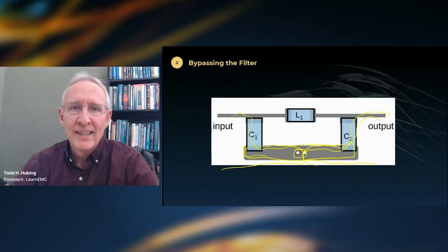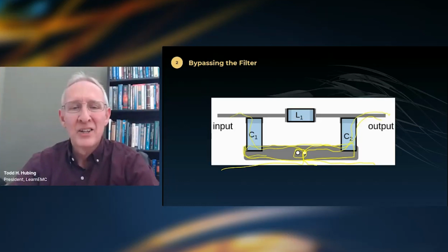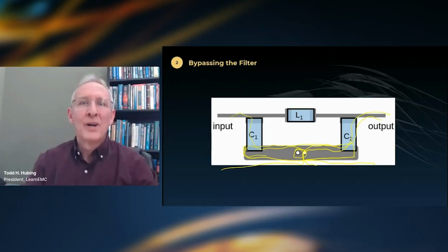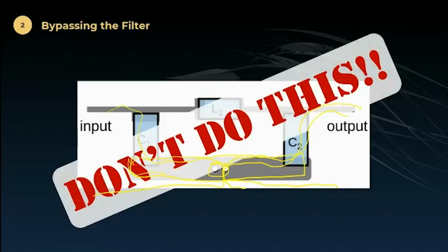Basically, that's again an example of people confusing ground and current return. They somehow were thinking this filter needs to have one ground, which is just not right. A filter doesn't need to have one ground, and they ignored the fact that they were directing the input and the output currents and making them share the same via, which is just awful advice.